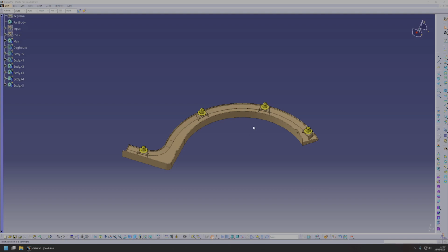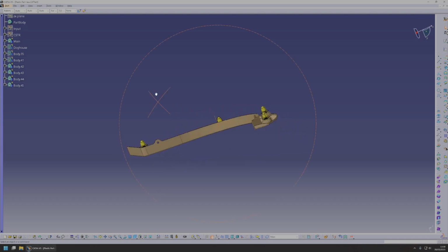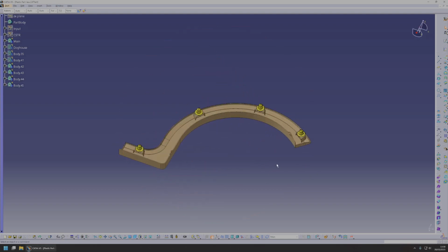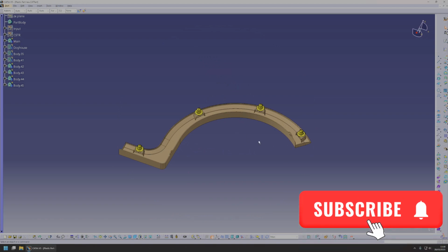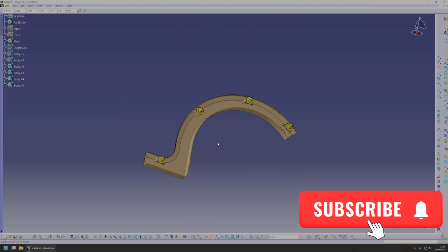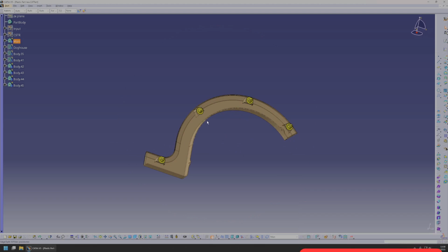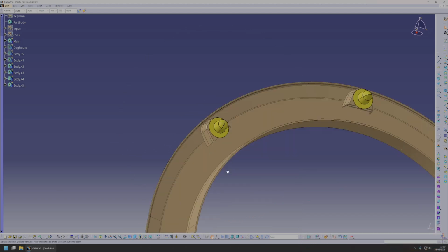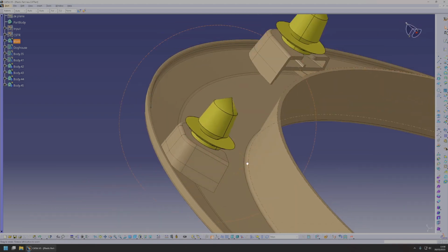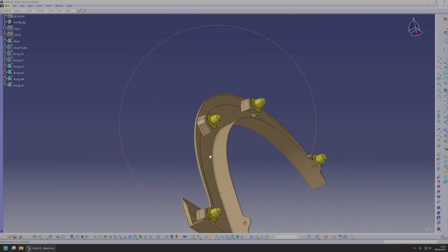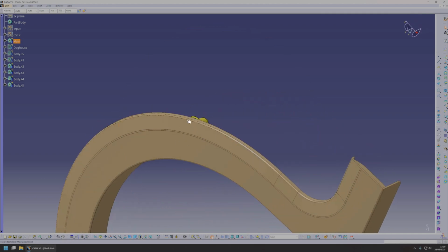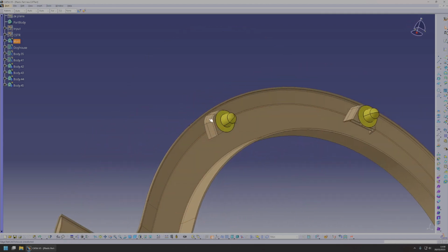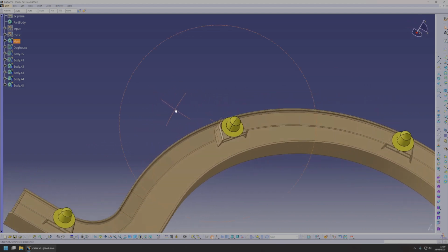Today we're going to be talking about plastic parts and we'll be designing this wonderful part here. We will go through the basics of solid modeling. We will touch upon draft angles. We will discuss a little bit about tooling. We will learn about the importance and design of doghouses, which is this little feature here. And we will discuss surface sink, which is the defect that appears on the A surface of the part when you add features on the back, like this.